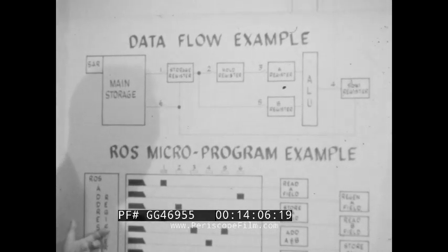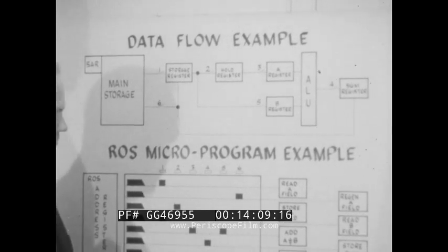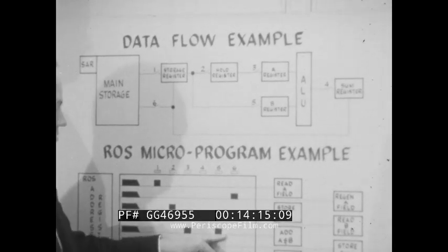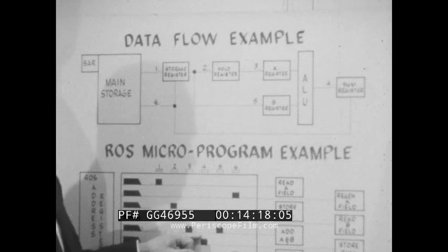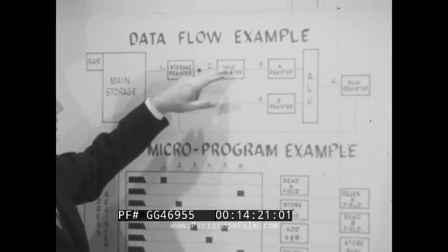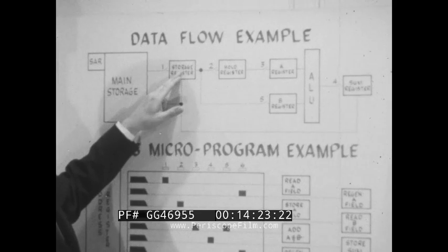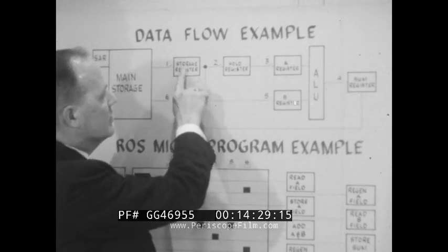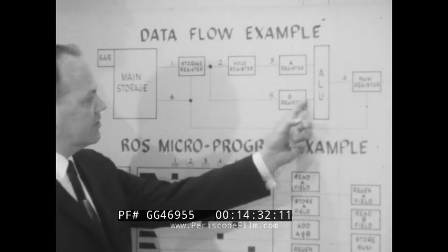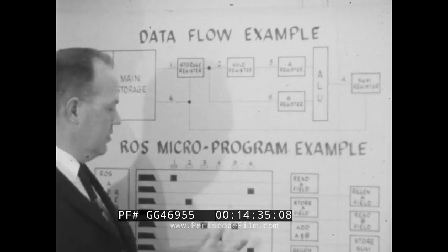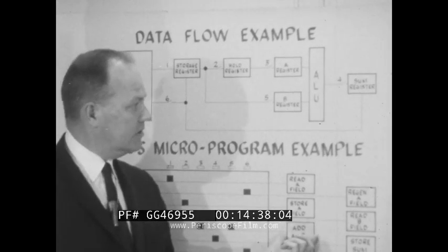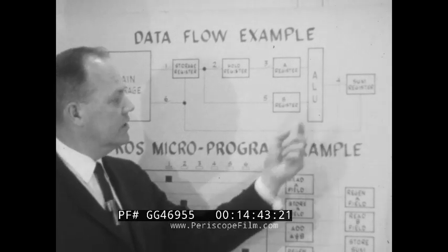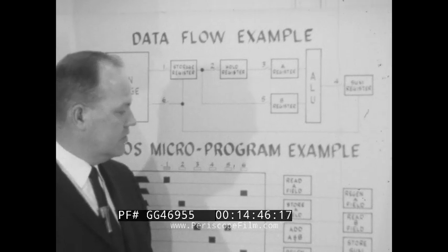It will hold there because there's no other place for it to go. Again, under read-only storage address control register, it says go to the next sequential instruction, and there we see a multiple function being carried out on this single instruction step, and that in this case is simply adding A to B. So we had the A field held here, we had the B field in here. So to execute this, we will close gates 3 and 5, moving the A field here, the B field here, and since we are now tied directly to the arithmetic logical unit, the rest of the function of the arithmetic operation is carried out directly, developing the sum and leaving the result in the arithmetic and logical unit.